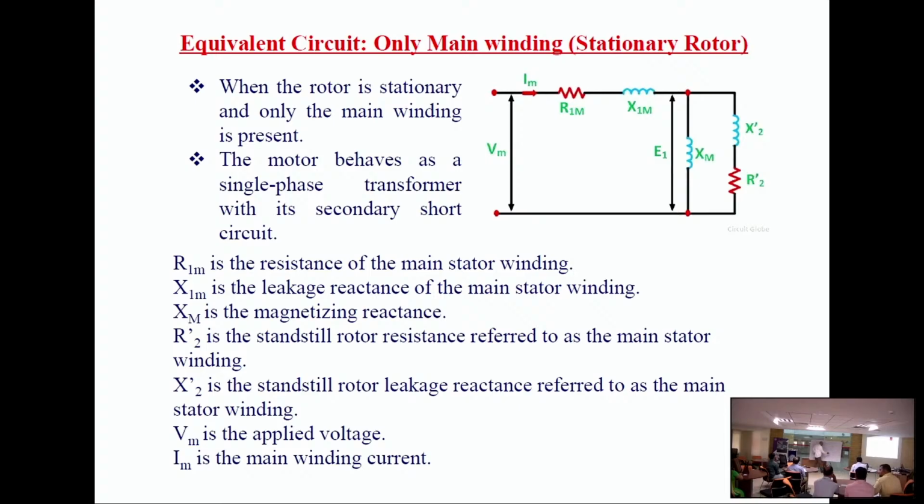Now this has the same supply frequency. So now this is correct. In one diagram you can now represent two voltages, because they have the same frequency. Then you transfer R2 dash and X2 dash. At standstill there is no difference; in the running case there is a difference.